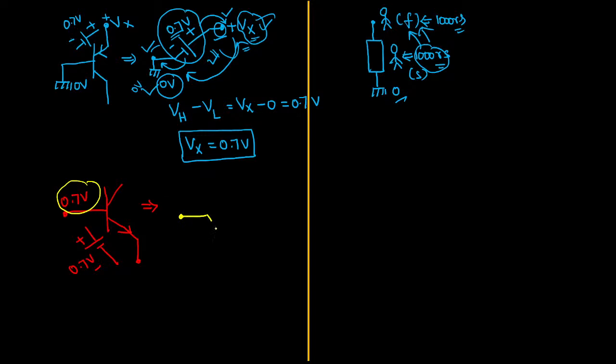After that we are crossing that diode. The diode will be having plus minus 0.7 voltage. Then we are reaching another junction. In that junction I am highlighting the voltage point as Vy. I don't know that value, but here I know this will be 0.7 plus 0.7. Now tell me, how will you identify the value of Vy?